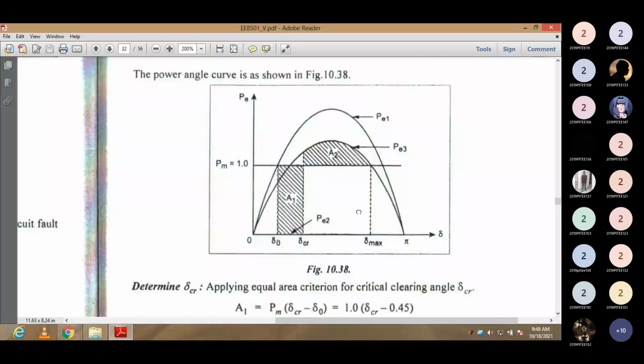So on your y-axis you have electrical power and on the x-axis you have load angle. So you have 3 powers. What are the 3 cases we have? Pre-fault, post-fault and fault. So during the fault, you don't have any electrical power. So the first large curve is your electrical power one.